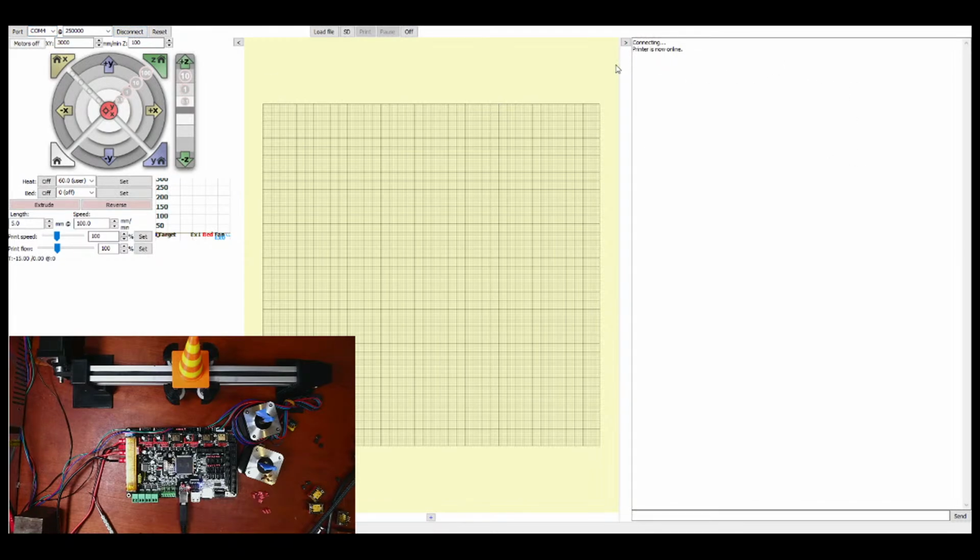This printer is now online. So I'm going to move the Z-axis. So I'm going to press 10 and see what happens. So as you can see, I almost created a wood chipper. So let's try moving back 1 and seeing what happens. So it's moving a significant amount of distance. So there are a couple ways you can deal with that. Obviously, it's the Z-axis and it's usually on a screw. So I'm going to have to move it slightly less. So I'm going to try homing and seeing what happens.